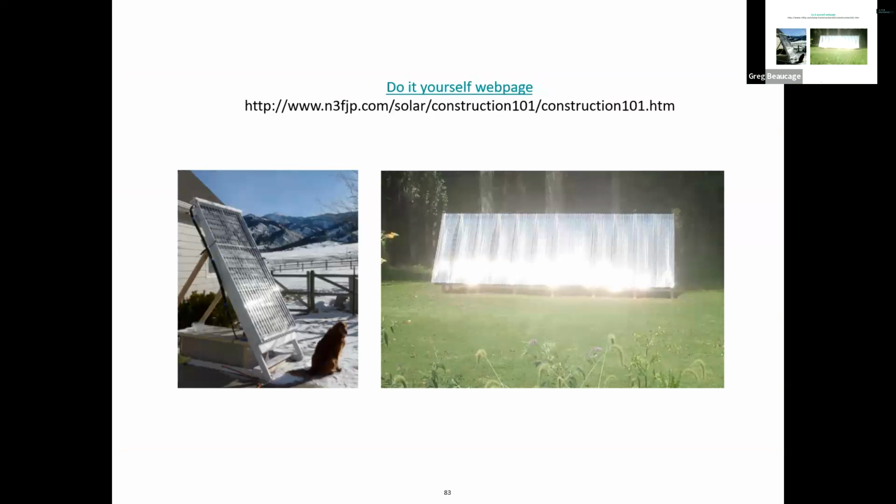Anyway, the notes go through different solar things, stuff you can do with solar. First, the simplest things like a greenhouse, and then you can heat water with solar. You can make your own. Basically, you can just get a box, paint it black, put water tubes in it, and run water through it, and it heats it up.